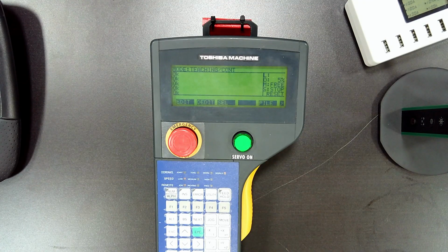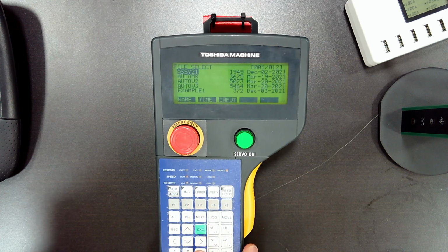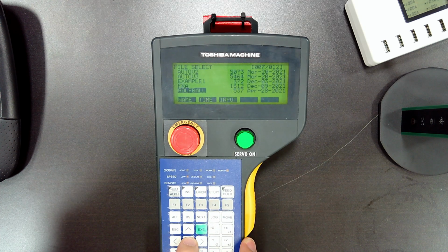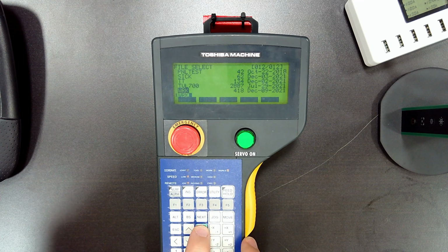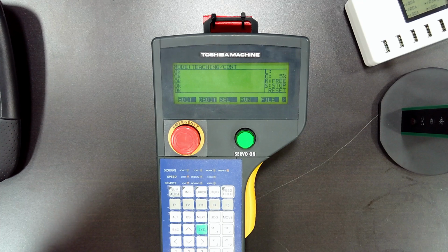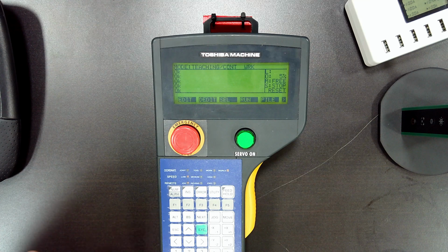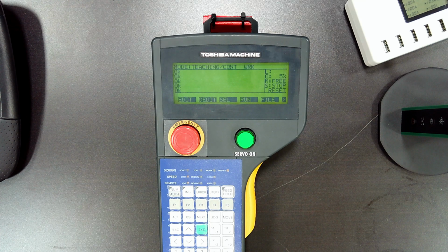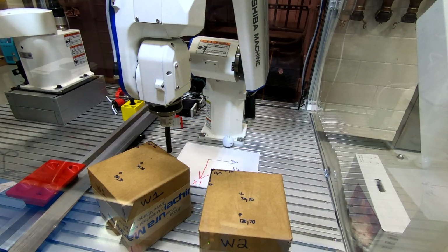So we've set the program using TSAssist. We're now on the Teach Pendant, we're going to call up that program. We're going to scroll down our list so we can find that program, WRK. Our program is selected. I've got things moving nice and slow. We're at 5% speed, so we'll keep things nice and slow just in case we've made a mistake. I'll switch the view here to the robot. We're going to turn the servo on.